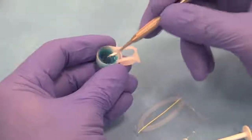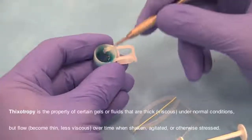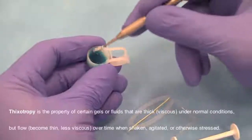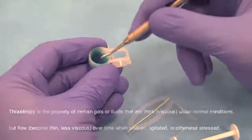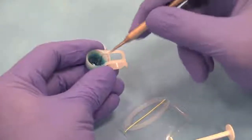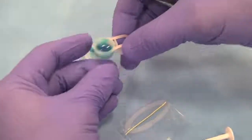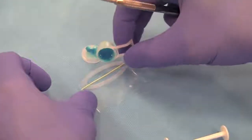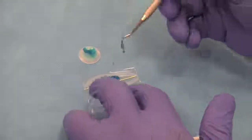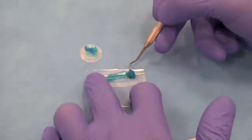Stir it up. It's a thixotropic material, so when we apply a load to the material, a shear force, it actually starts to liquefy. So now this product, which was too much of a gel, is very nice to use. It's easy now to dispense, and you can just drip that onto a little plastic cover here that we have for the cords,